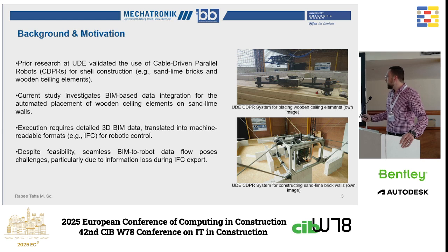The reason behind that is our earlier trials proved that this automated execution requires highly detailed 3D BIM data that should be translated into machine-readable formats with zero loss, with full integrity of the data. And despite it being feasible, achieving this seamless BIM to robot data flow still poses a challenge, particularly due to the information loss during IFC export.